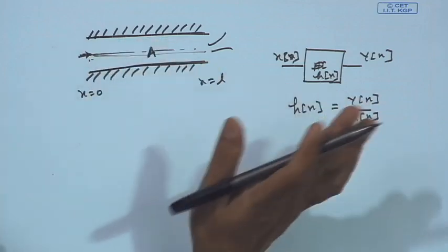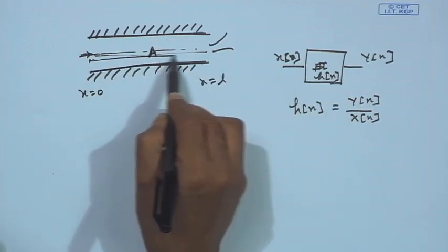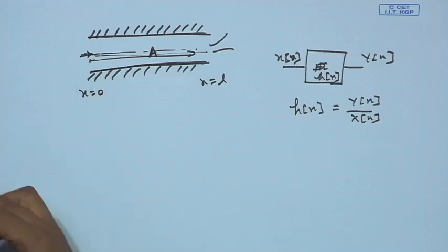Okay. Now, considering the amplitude of the pressure, if the wave is propagated linearly, then we say linear wave equation. Here I am saying the amplitude of the sound is not large enough that the propagation becomes non-linear. So, I say the amplitude is within the limit, the sound is propagated linearly in the medium, and the medium is also homogeneous. Then we can derive the linear wave equation. Similarly, here also we try to derive the linear wave equation, how the wave is propagated along the tube. Let us try to do that. So, how do we do it?